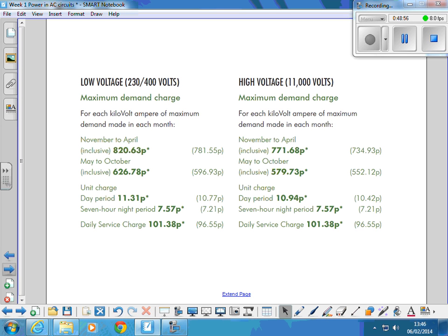We haven't discussed power factor correction yet. There's two ways of doing it. One is to have it overall on the load center where your switchboard is. The other is to have it locally, mounted at the point where the motor is, and sometimes both. Usually the load center stuff is automatic, so it'll switch in and out according to the changes in reactive load.